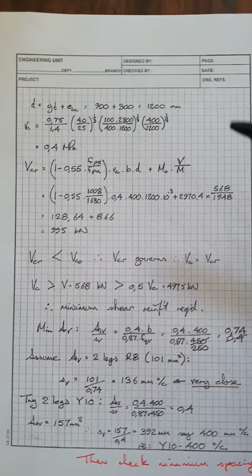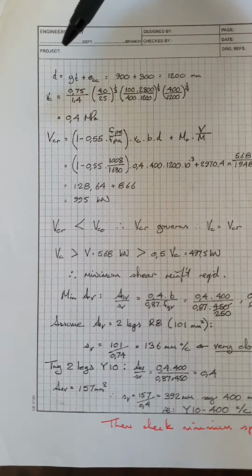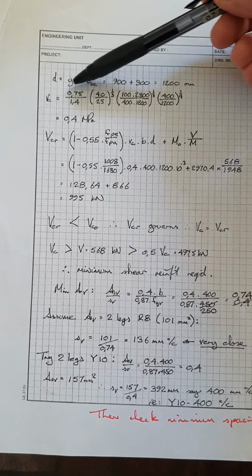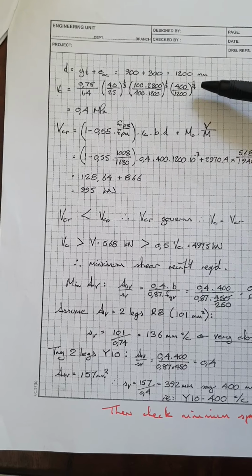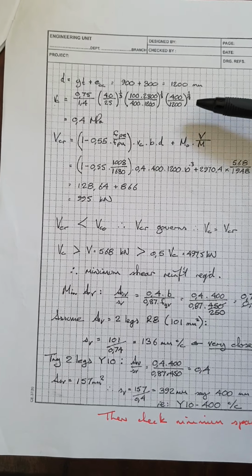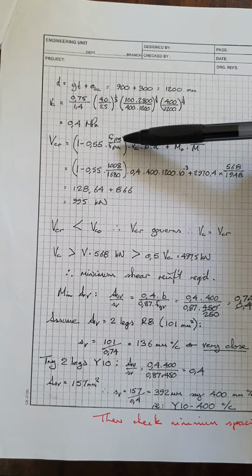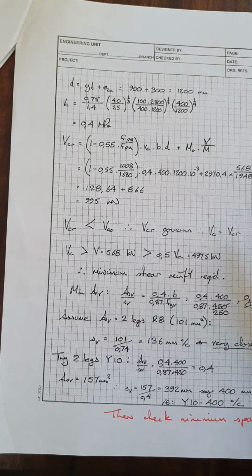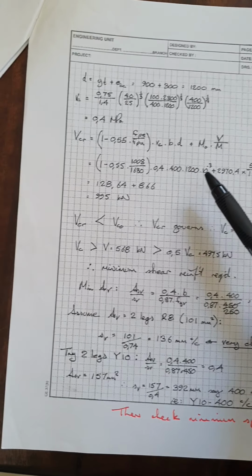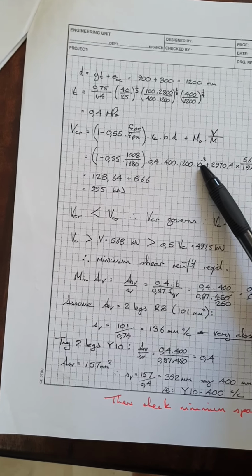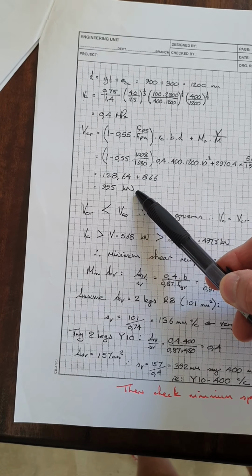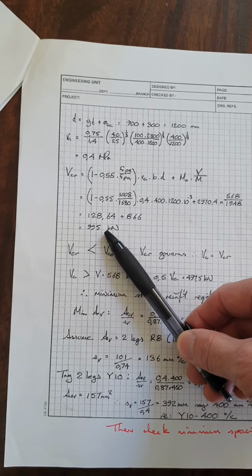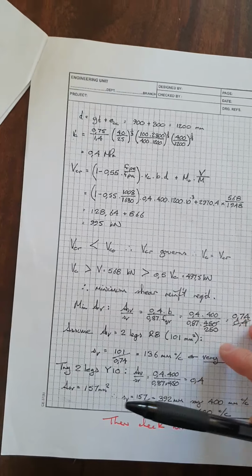Okay, just a few little things we need to calculate here. D, obviously this is the depth from the compression face down to the pre-stressed steel. Quite a straightforward calculation. VC, this is exactly as per normal reinforced concrete. Okay, now we can build up our little formula for VCR. We've calculated everything we need. Put it all in. Just watch your signs. Watch your units as well. Calculate your VCR, in other words, your shear strength of the beam for the cracking moment.